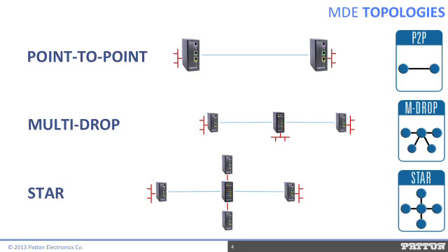Using multiple repeaters extends the overall end-to-end length of the network and also drops Ethernet ports at the intermediate locations. We can build the star topology by connecting endpoint Ethernet extenders to the MDE devices' Ethernet ports. The diagram implies but does not show the extension of more Ethernet extender units. By using endpoint and MDE-style Ethernet extenders, a broad variety of networks can be addressed by your application.